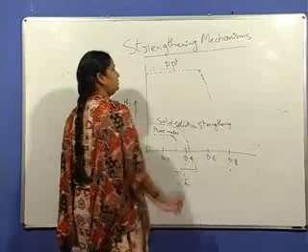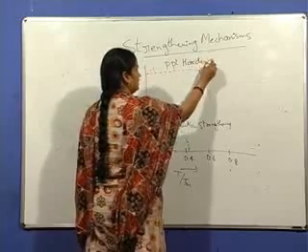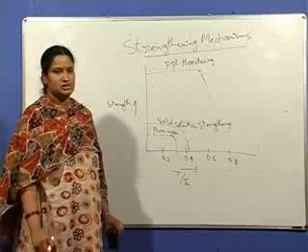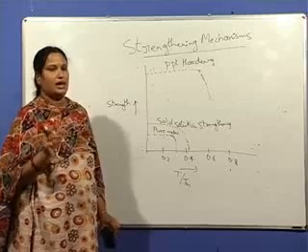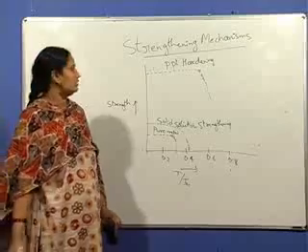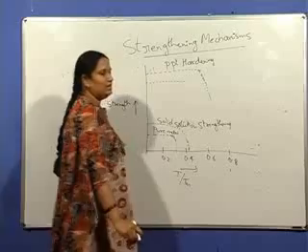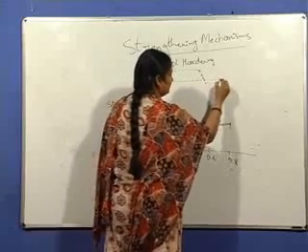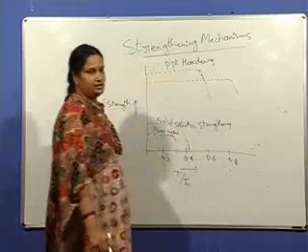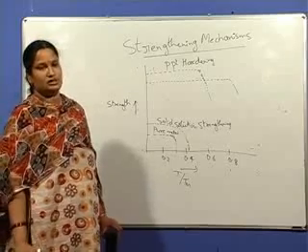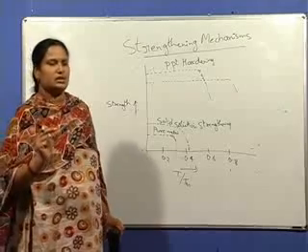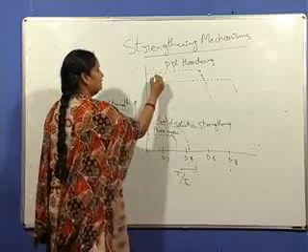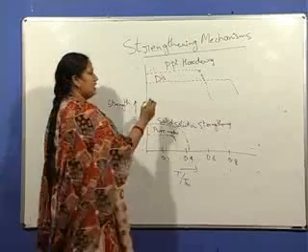This is the precipitation strengthening, or precipitation hardening, which has higher strength, but the strength drops down at greater than about 0.6 of the homologous temperature because of the coarsening of the precipitate. As the precipitate coarsens at higher temperatures, it loses its coherency, thereby the strength comes down. Whereas dispersion strengthening has relatively low strength compared to precipitation strengthening. But even at higher temperatures, at about 0.8, it can retain its strength, because the dispersoids do not coarsen, or coarsen to a very small extent. So this is about the three types of strengthening mechanisms with respect to temperature and their strengths.